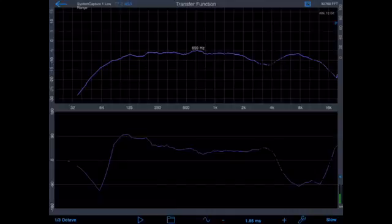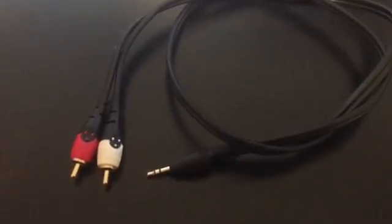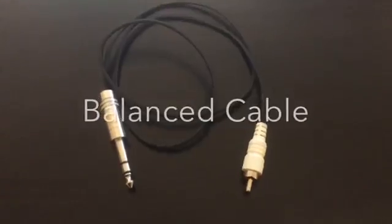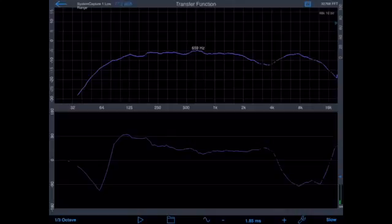Since we will be using the internal pink noise generator, we need a way to get that signal out of the iOS device and into the sound system. You will need a cable with an 1/8" 3-conductor plug for the iOS device headset jack, with either two RCA connectors or one 1/4" or XLR balanced plug on the other end. It's important to set the generator correctly for the cable type.